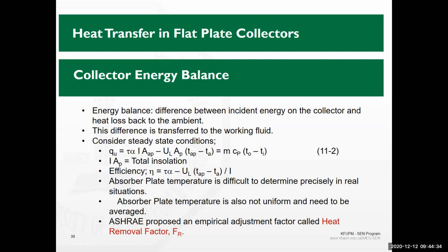So how many thermocouples should you put in to measure it? Practically speaking, the temperature at the absorber plate, TAP, is not something easy to get. That's why there was a proposal by ASHRAE, the American Society of Heating, Refrigerating and Air Conditioning Engineers, who proposed an empirical adjustment factor called the heat removal factor, FR.